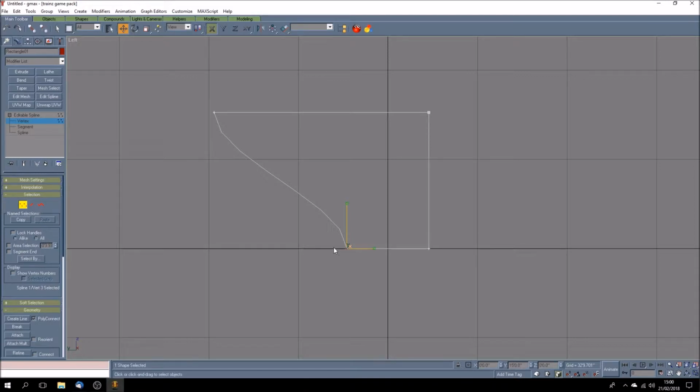So just by highlighting that point, you look at this one, there they are, look, they're in line with the mesh, and that one, we've got these little handles for. And so if we wanted a nice smooth straight line there, instead of this rather oddly curving line, what we'd need to do is, with the x-axis highlighted, grab the handle and move it over, so it's more or less pointing at the other one.